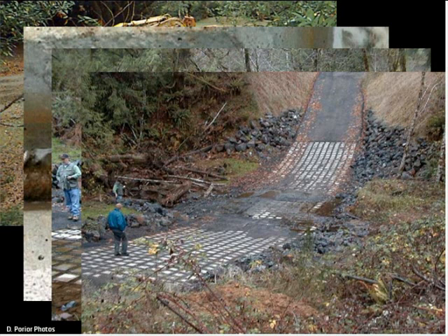So here's a few shots of a crossing project in Oregon showing a cable concrete mat and excavator prior to installation, juvenile Chinook moving upstream between the blocks the day after it was built, and the crossing after the first rain-induced high flow event in the fall. Voids between the blocks can be backfilled with smaller material following construction, but they tend to infill naturally in streams with relatively intact sediment transport regimes.